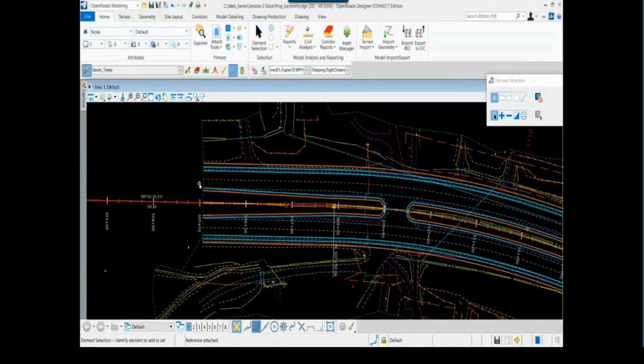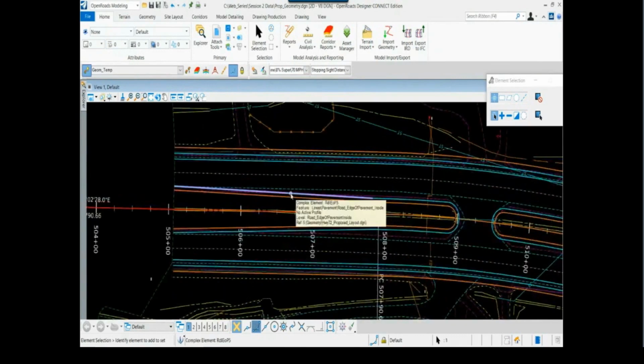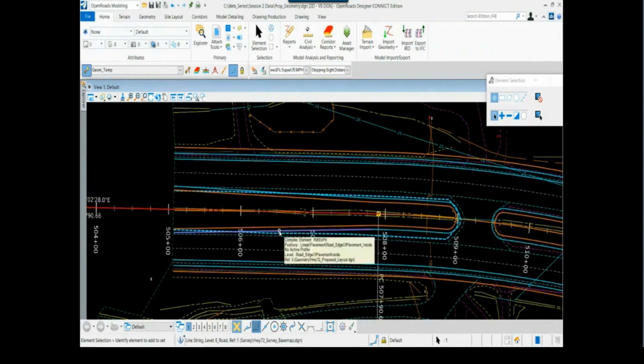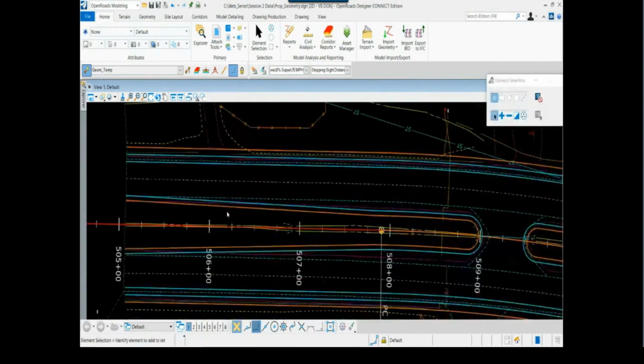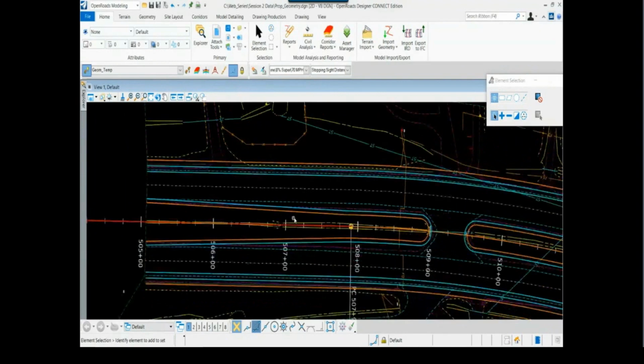Okay? So I'm going to create these taper elements using civil or OpenRoads geometry. Currently, these are just MicroStation lines, just a graphics file of the proposed layout. I'm going to create these so that Scott can use them next week as control lines to control his width of pavement. All right, so to do that, I'm back under the geometry tools.